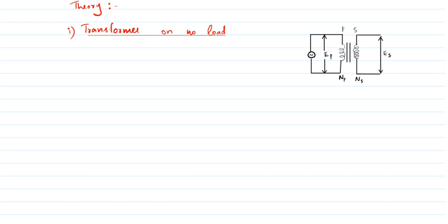When an alternating EMF is applied across the primary, a current flows in its winding and this develops a magnetic flux in the core. Here it is assumed that there are no losses and no leakage of flux. Let phi be the magnetic flux linked with each turn of the coil. Then this magnetic flux phi is linked with both primary and secondary.